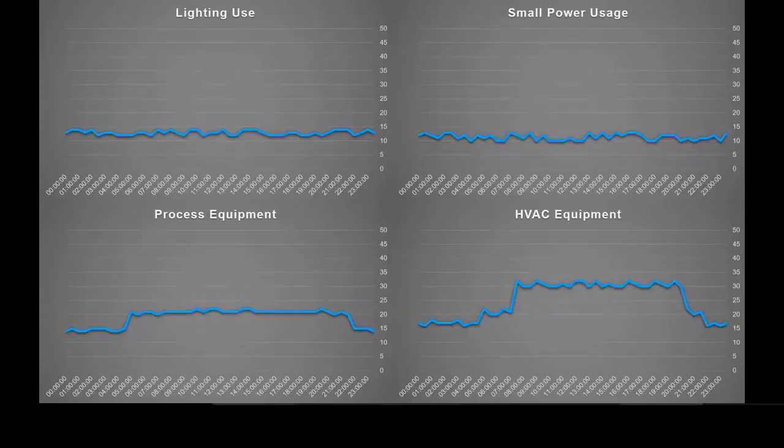If we look at the process equipment, again, the base load is still quite high, and then it kicks in around 5 a.m. And then the HVAC again, there's things happening overnight, which is really equating to a really large rise in energy, and probably, from an efficiency perspective, is grossly underperforming. So obviously, by being able to split these things out, the analysis element really comes in, so you can get down to a more granular effect.